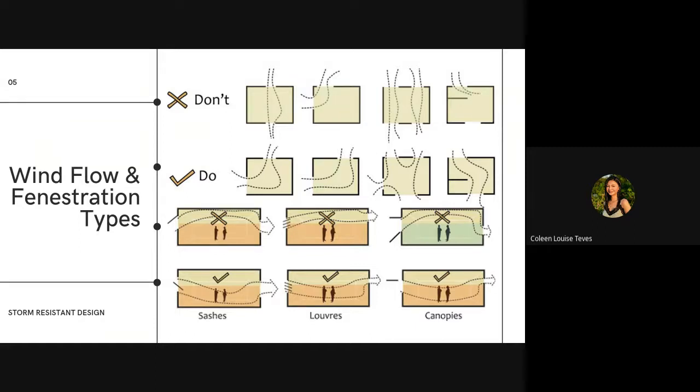Next is the corner window with an obstruction. It will not even reach half of the room or the opposing window. What we have here for the dos is better coverage for the wind flow: indirect windows but opposing walls, better ratioed windows, and windows that are not covered.